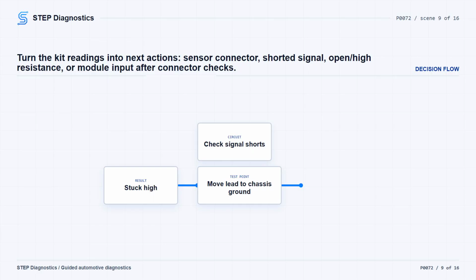If the signal is stuck high, or only the circuit high fault sets, the most likely cause is an open or very high resistance in the temp sensor signal or temp sensor ground circuit. With voltage still present when the tool is switched closed, move the test lead off the sensor ground circuit and onto a good chassis ground while watching the scan tool.